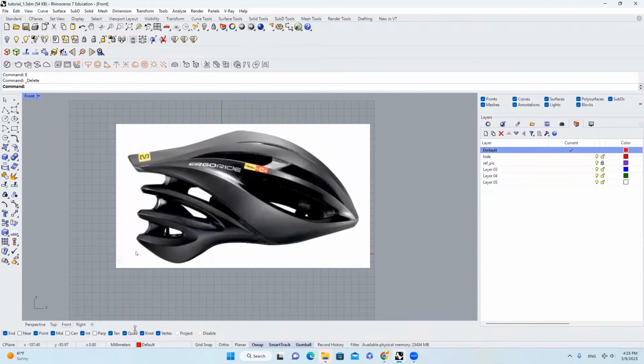First of all, make sure that you set your unit to 300 millimeter. Go to the front view, bring this image in, and make sure that from this point, orthogonally to this point, is 300 millimeter. And then I'm going to start the drawing process.